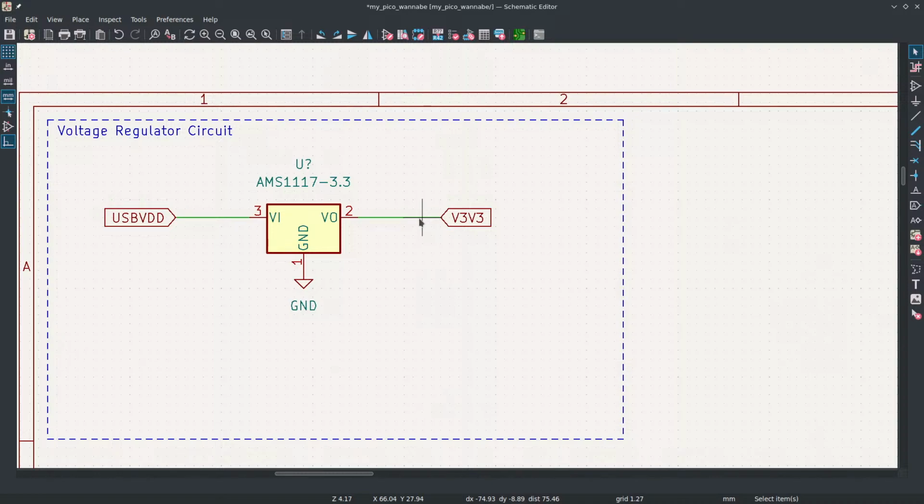If you have 5 volts and you draw 1 amp at 5 volts, you're going to use 5 watts. In a voltage regulator, if you draw 1 amp at 3.3 volts on the far end, you're still going to use 5 watts, and the leftover 1.7 volts worth dissipates 1.7 watts in your voltage regulator.